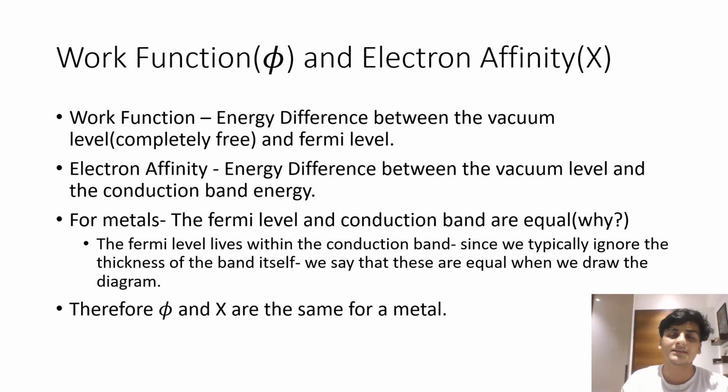So for metals, because they have semi-filled conduction bands, the Fermi level and conduction band are shown as the same and are considered equal. As a consequence, the work function and electron affinity are also the same for metals.